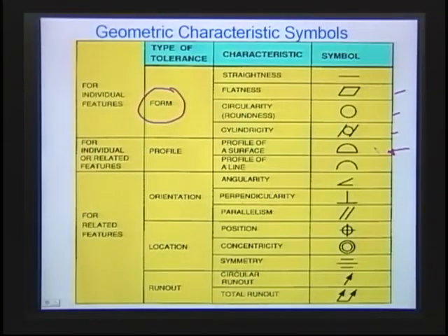We're going to use geometric tolerancing in everything. This is a geometrics class, so we're going to use it to its fullest, right? It's a 3D mathematical engineering language. We're going to use profile. So profile is a 3D callout. That's what we're going to use. Not too much on profile of a line. I don't see a lot of use of it.